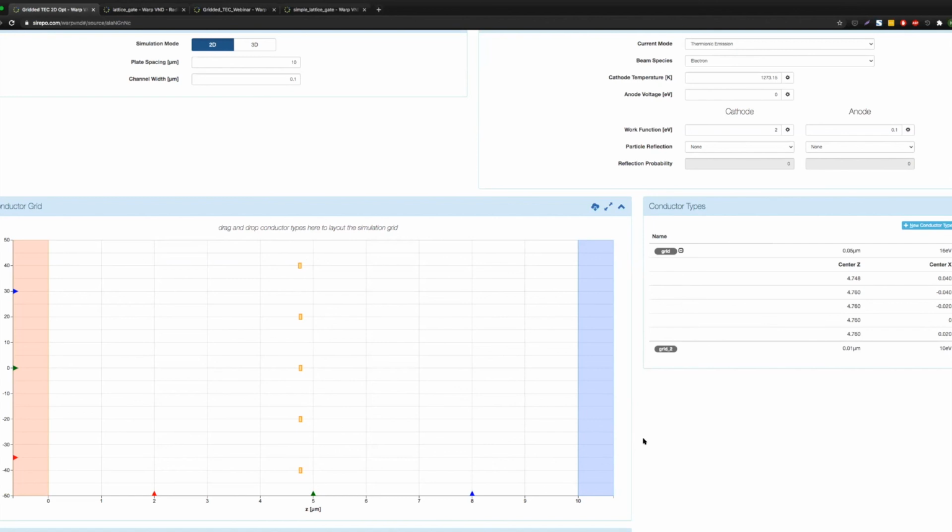And Alex just asked a follow-up question: would that have been faster to run? So yes, in general, I think so. Right now we're running all of these natively on a single processor, so you're not getting an advantage from MPI parallelism. There's no domain decomposition here. In most cases it would be faster, because this is a V-cycle multi-grid solver that Warp's using to obtain the fields.